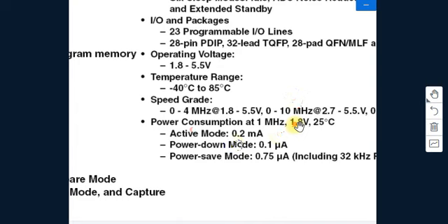So in different examples of Arduino programs, you observe that a starting program is written using pin number 13 because it has an inbuilt LED. You can test the board using that LED pin also. So these pins we already discussed. This point is the reset button. Sometimes it may be here. This is the USB connector, and this is called the barrel jack.